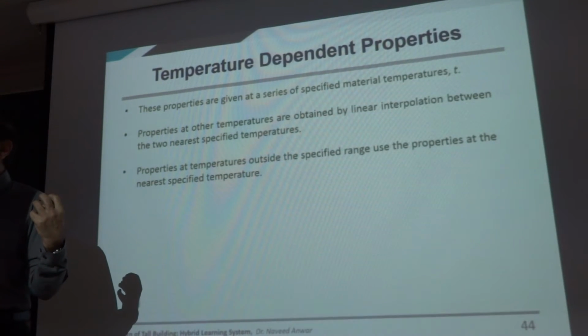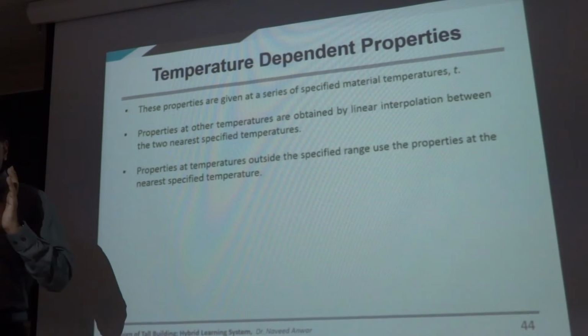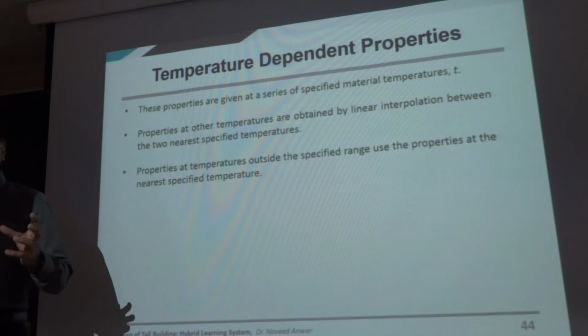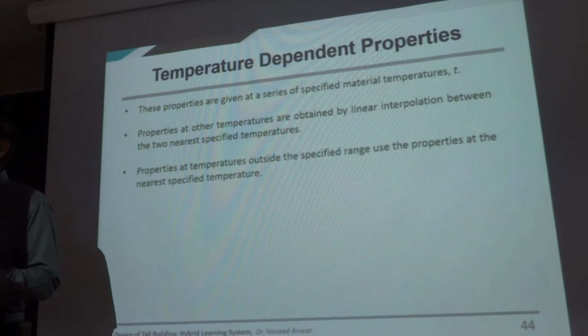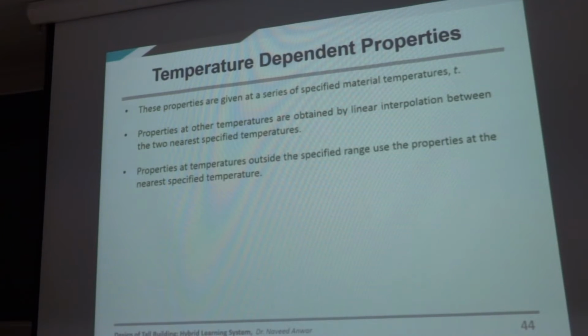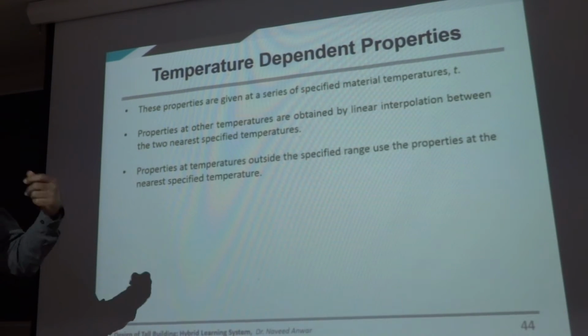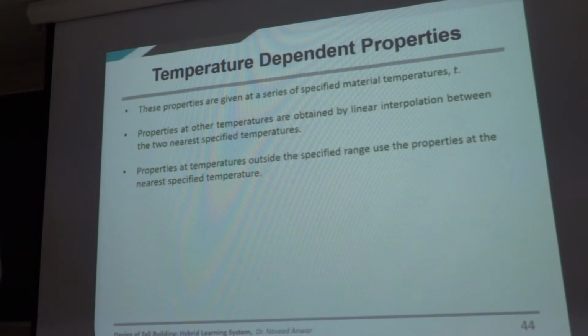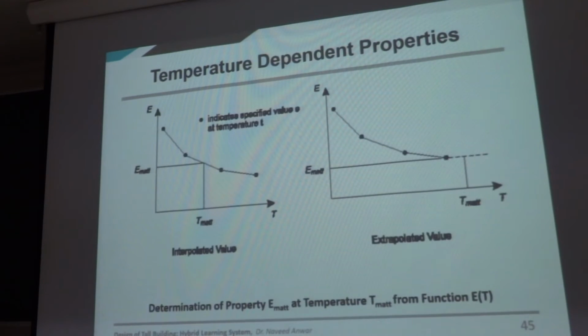dependency becomes very important. That's why in a modeling of a dam, the temperature variation, heat of hydration becomes very critical. You know, when you pour concrete and it gradually cools down, the center part is still hot, the outside cools down. That temperature variation becomes a major issue in dams and big concrete blocks, which creates huge cracking if you do not do the analysis for temperature dependent properties using anisotropic modeling, right? So there are problems that we have to consider all of that.